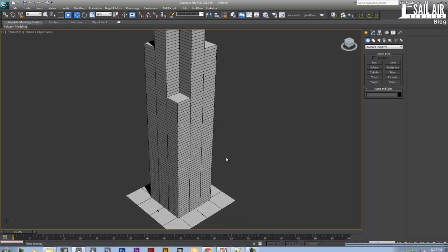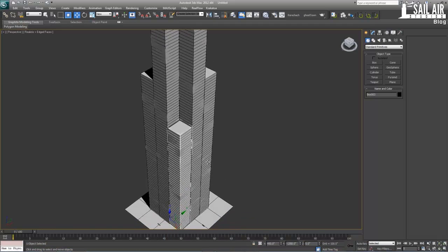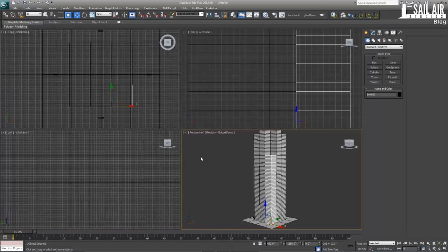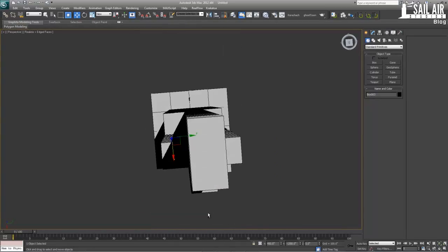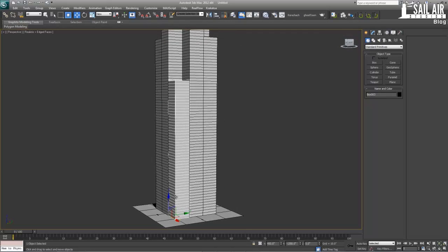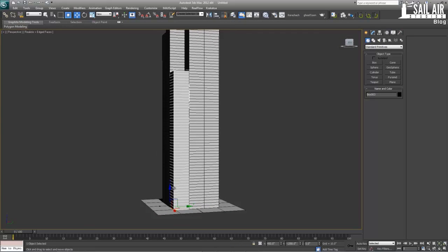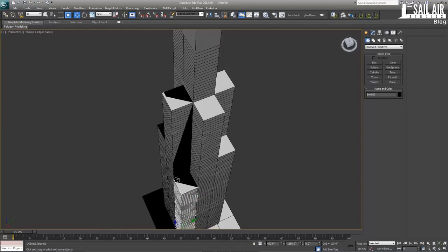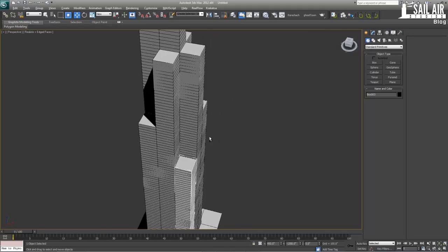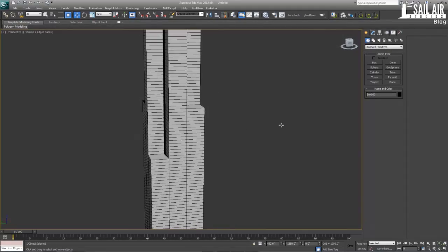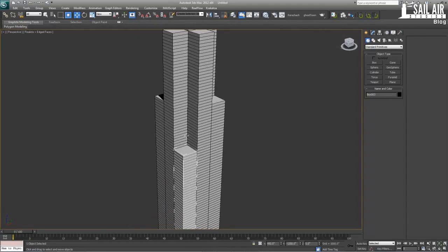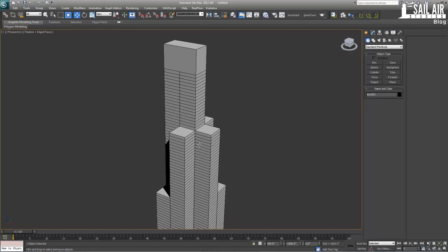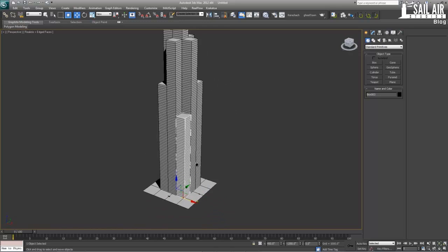Now next what we will be doing is we will be creating the splines around the silhouettes that our RailClone stuff will follow. So as you can see, there's a silhouette, or not a silhouette, more of a uniform, I can't remember the actual word. Profile? Yeah, maybe profile, but it's from top. There's a profile that goes around these 9 towers, which is just a block, 1 square. There's one that goes around these 1, 2, 3, 4, 5, 6, 7 towers, because it ends here. The 9 towers turn into 7, and then these 7 towers turn into 5, and these 5 towers turn into 2. And we just need a different blockout for each of those.